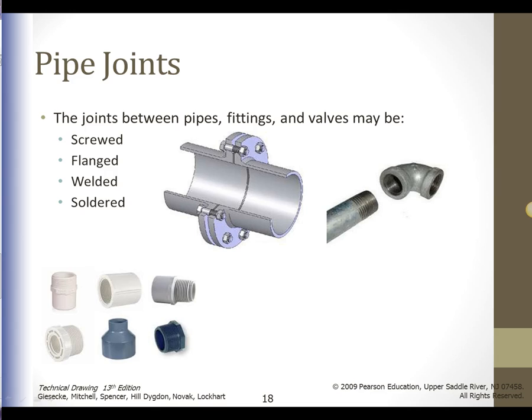Flange joints are made by bolting 2 flanges together with a resilient gasket between the flange faces. The flanges may be attached using a screwed joint, by welding, lapping the pipe, or by being cast integrally with a pipe fitting or an appliance. Now you can see different types of joints, either a socket weld or a butt weld, in figures 21.13, 21.16, and 21.17. You can also see Appendix 37, Appendix 42, and Appendix 45 for cast iron.